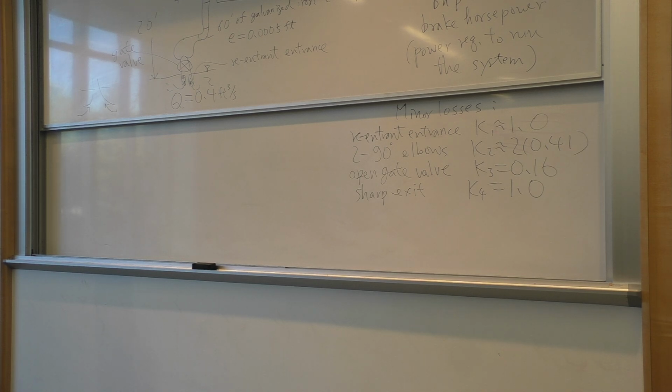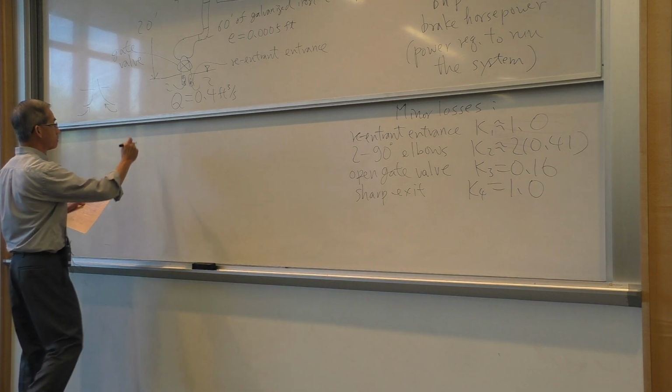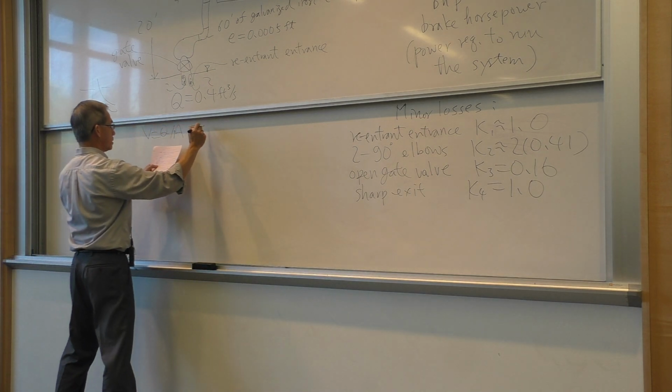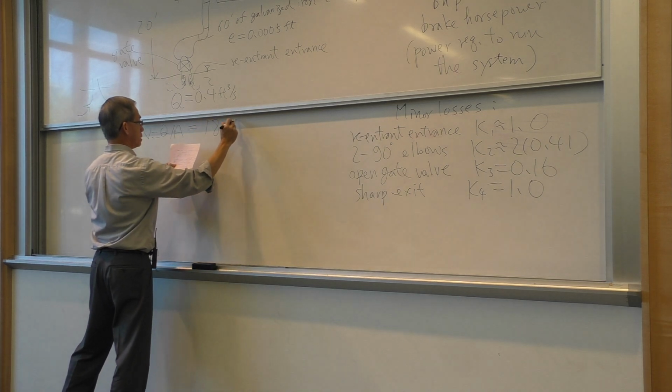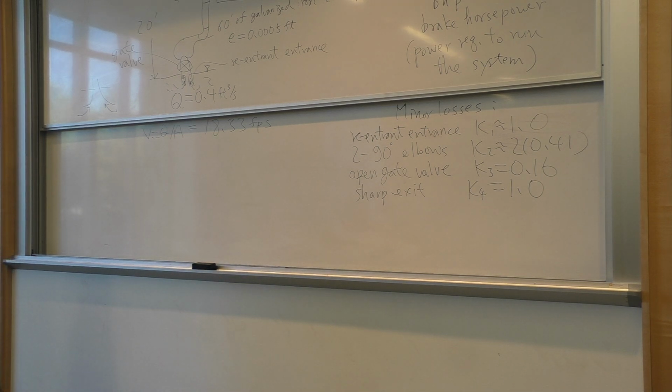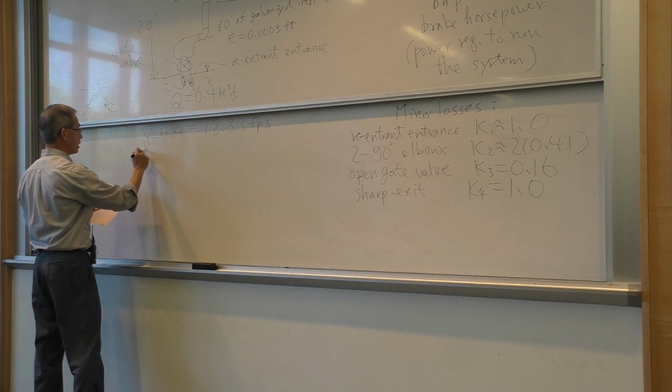Because the Moody diagram losses is the same old calculation we have done of getting the Reynolds number. So the velocity in this water system is about 18 feet per second. From that, the Reynolds number.